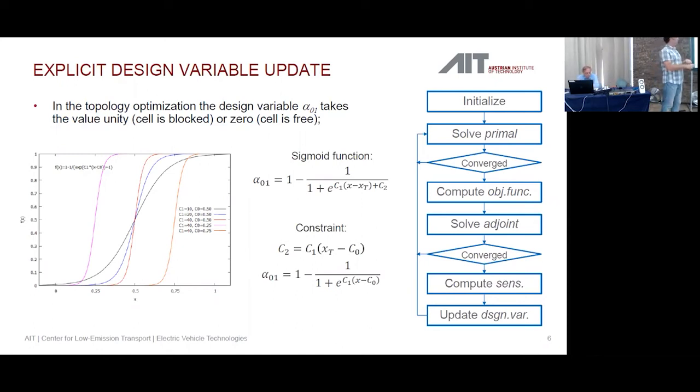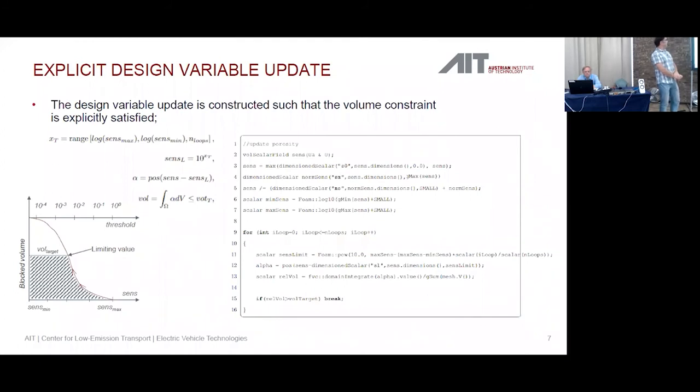But if I have a freedom, of course, I impose my constraint to select one of them, and my constraint is, as I said before, the occupied volume constraint. So in the end, what I'm doing next, of course, this is all just explained a little longer, but in the end, I will be using it in a stepped manner. I won't be going through the sigmoid at all. I'll just check yes or no, greater or lower than, go through the cells, and specify my alpha in an initial guess from the maximum value, and then maximized it will start from 0 downwards.